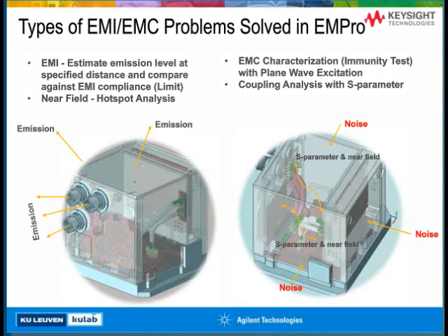And then coupling analysis. One of the examples shown here contains many different boards within the housing, and definitely there are coupling problems between board to board or cable to cable. This type of problem can be analyzed with the S-parameter simulation in the tool. And in order to understand what or where the source of the noise is, we can do hotspot analysis with the near-field analysis capability in the tool. So these are very difficult types of problems that can be handled in the EMPro environment.